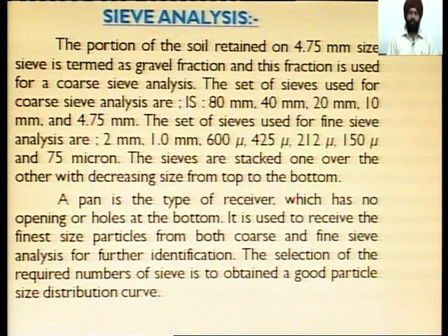The set of sieves used for coarse sieve analysis are IS 80 mm, 40 mm, 20 mm, 10 mm and 4.75 mm sieves.